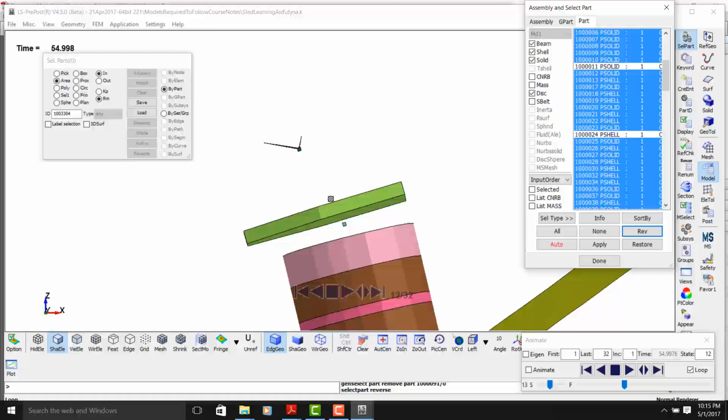That is for the real dummy. That is what they are doing in the lab. They are measuring the neck moment here, but they also have the neck Fx shear force. They multiply Fx by 17.78 millimeters, and they subtract it from the neck moment as given by the load cell. And that is the moment here, which is what they want.